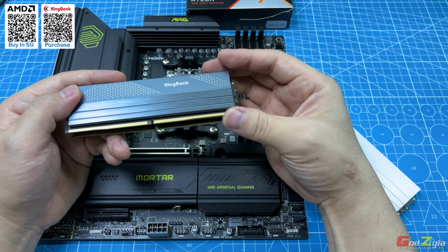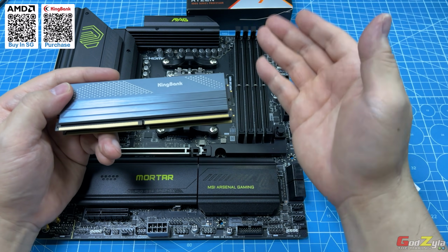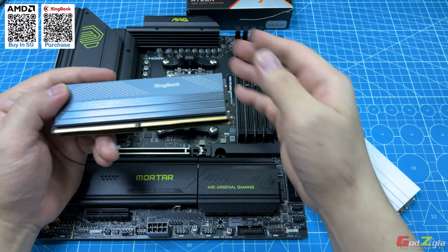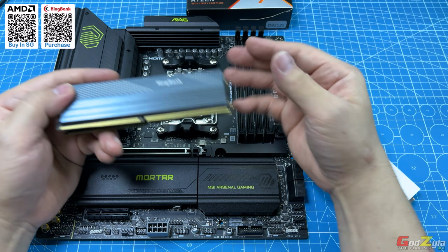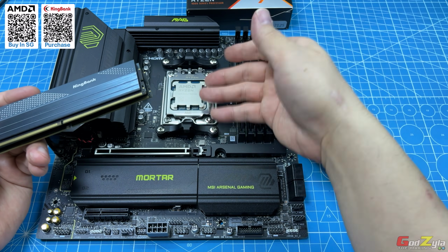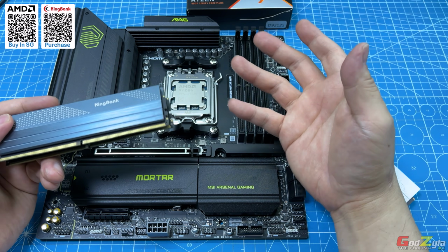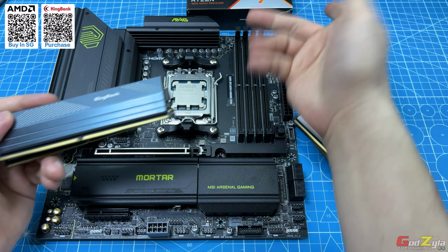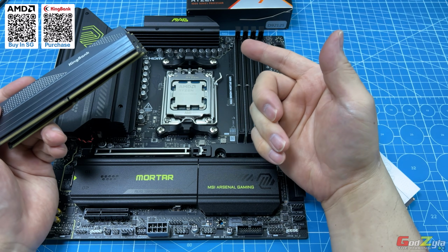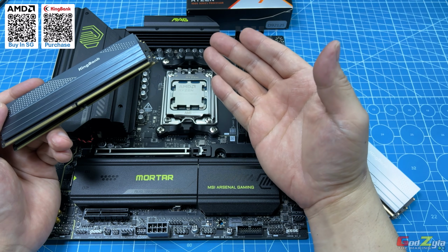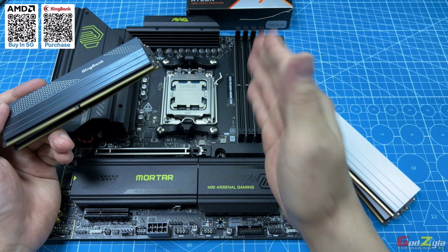And as you see, if you set it to auto, blindly everyone will do that. Follow YouTubers saying that, oh, you just enable the XMP profile, don't have to worry about SoC and such. They don't touch on that. And furthermore, you're stretching everything. Curve optimizer, curve optimizer, make it to -30, -40. Another thing is the RAMs. The higher the RAM bus speed is, the more SoC you're going to pull. You weaken yourself. There is a warning on Reddit itself saying that please do not run SoC above 1.2.